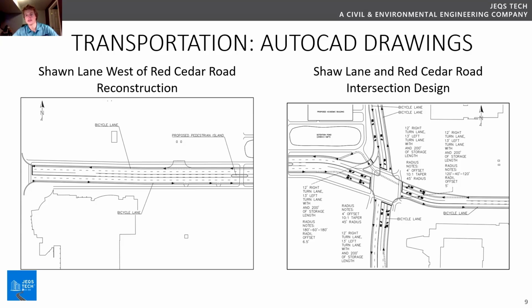And we have bicycle lanes traveling in each direction with a slip lane in the northwest corridor. And this pedestrian island in the northwest corridor, again, is for pedestrian safety and optimization of level of service, as it would take a long time for the pedestrians to cross the intersection if it was just all roadway, if there was no slip lane installed there.